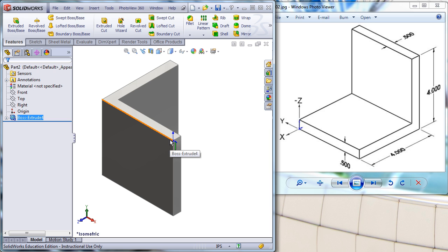There's about 6 of these problems in the handout for you to go through. Take your time, work through it just the way I did it. Decide your plane first, then decide the direction of the first line and the second line. That sets the orientation of the whole shape. And then once you've created the L shape, make a decision on what direction you're going to extrude it and take it that way. Good luck and enjoy.